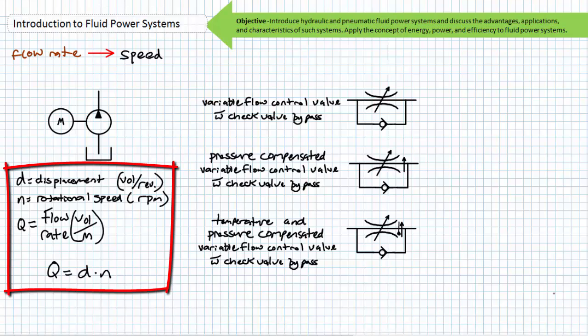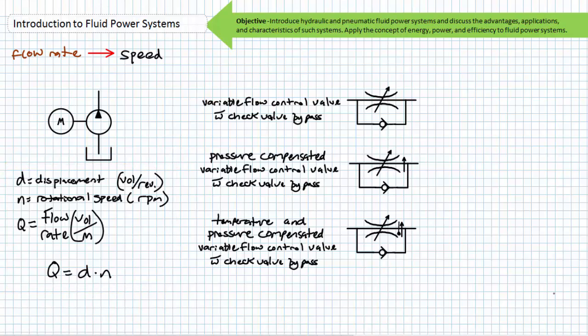Similarly, if the prime mover remains at a fixed constant speed, a variable displacement pump can vary the displacement per revolution to change resultant flow rate. Flow control valves can then be used to throttle flow rate down from there. Flow control valves ordinarily feature a restricted orifice that can be varied opened or closed as conditions dictate.